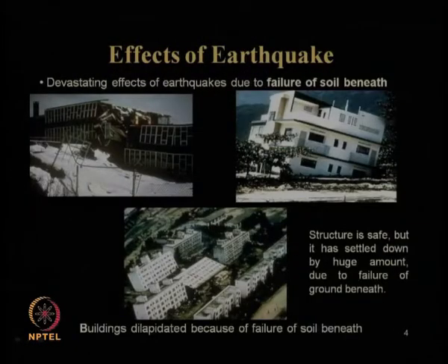We have also seen the devastating effects of earthquake due to failure of the soil below the structure or in the foundation soil. So, it is not necessarily that the superstructure or the building failure will occur due to the earthquake. It may be because of the behavior of the soil during the earthquake or the foundation failure. As shown through these slides already, the superstructure was designed perfectly fine to withstand the earthquake.